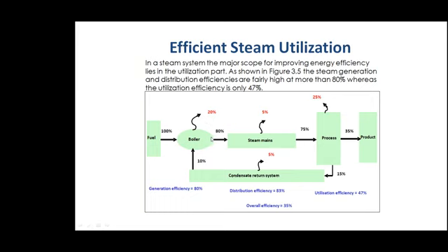That means only 80% is the efficiency of the boiler. In other words, the steam carries 80% of the heat in the fuel. So 80% is going through the pipelines. There is again a radiation and convection loss, about 5%, in spite of all the insulation. And it reaches the process. So 75% of the heat in the fuel has come to the process.